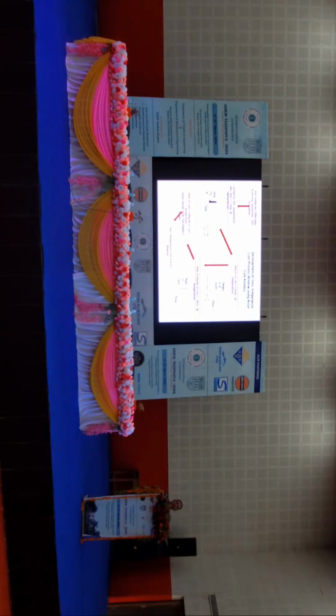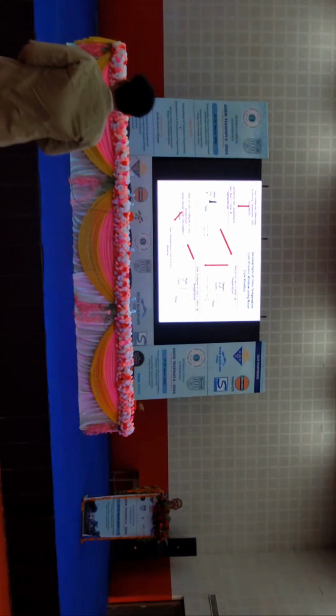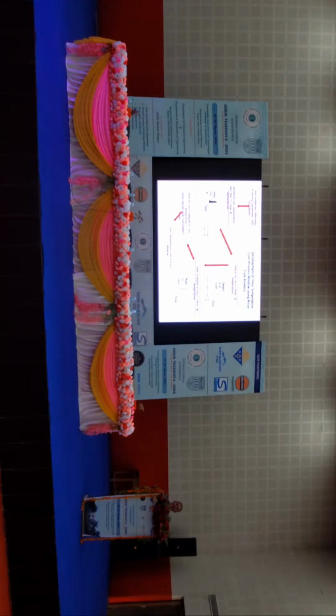So that is not the usual way. Whatever classical way we follow, you cannot do it. Whereas we do the kinetics part in an indirect way, from the heat evolution behavior of the resin. Since this curing reaction is exothermic, you always have some heat getting evolved from initiation to termination. So by scanning the heat evolution behavior, I am able to find out the curing kinetics, in terms of degree of cure, how fast the curing is progressing.